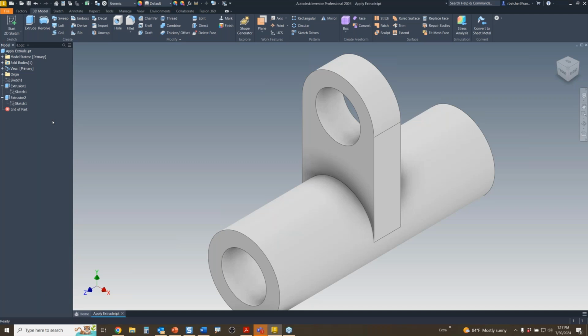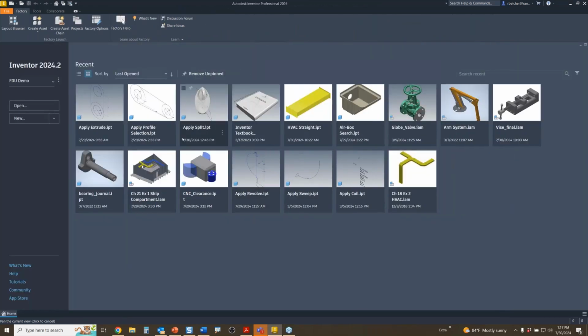Just clicking apply. I think many of us are used to the apply button like on a fillet command, where you do a string of them one after another after another. So trust me, you want to start looking for the apply button. The past several releases of Inventor, they've been adding the apply button to more and more feature command dialogues. So again, I'm going to close these as I go. I've got another one here. Let's take a look at the revolve command.